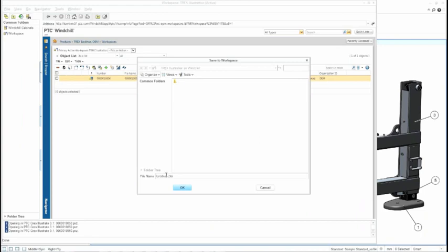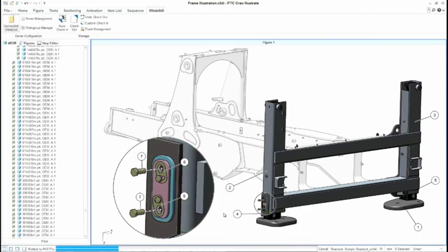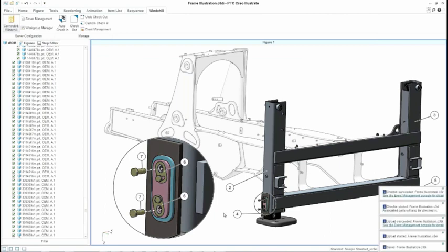I'm going to save it as the name that I want anyone in Windchill to be able to search and find. And then once I auto check this back into Windchill, I can watch the whole process on my bottom right-hand corner here. I'll be able to see when the upload starts, when the save is complete, and when the check-in is complete.